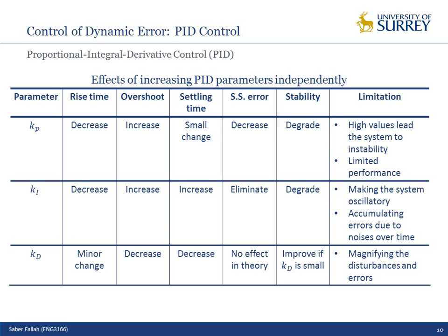Decreasing means that the absolute value of the error goes to zero. It doesn't matter if it's negative or positive. And you can only eliminate steady state error when there is an integrator, if I have just the integrator. In terms of tuning, in some cases you can, for example, design the Kp which gives zero steady state error. But for sure, the dynamic response will be damaged completely. We are talking about a good design, the trade-off between conflicting requirements.